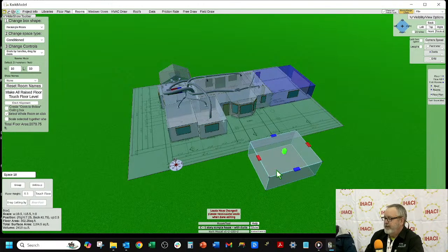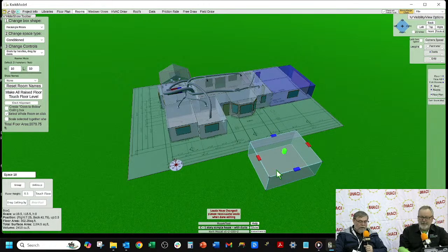You have to do a load calc to know what the house needs so you can pick the right size equipment. It's that simple. So I agree with you 100% because at my company we do load calcs on almost every house. I've seen your load calcs. You do a great job. Yeah, well, I've been doing it since like 2000, so I better know what I'm doing by now.